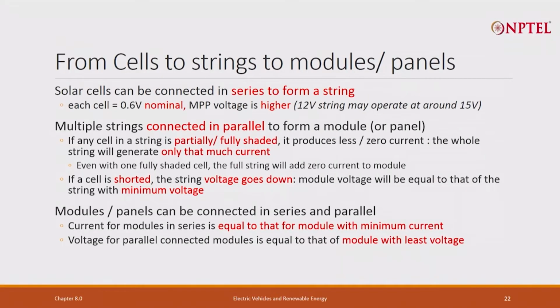Module panels can be connected in series in a panel. Again, if you take a 24 volt panel and put 4 of them, you get 96 volt. You take 48 volt and put 10 of them, you get 480 volts, and typically large voltages and large currents are used.